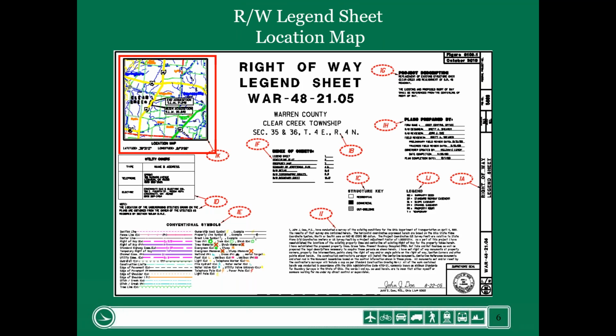And don't be confused. There's a political township and then there's a survey township. In some areas of the state of Ohio, a political township's boundaries can change and have changed over time. Original public land survey townships do not. They're infinite, they're forever, the way they've been surveyed and their location.